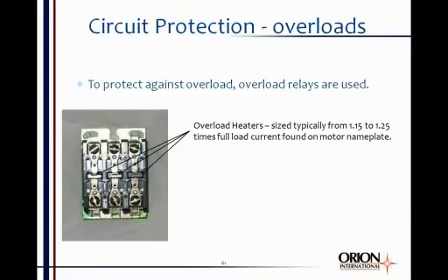So what you do to protect against overload is you'll use what's called an overload relay, and these hang right below the starter, right below the contactor as part of the motor starter. And typically electricians have to size the overload heater. The overload heater, of course, is what we saw in that 3-phase circuit. They're in series with the mainline contacts going out to the motors. The load current actually goes through the overload heater.